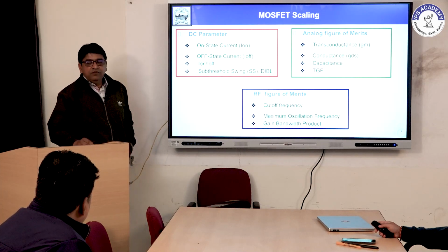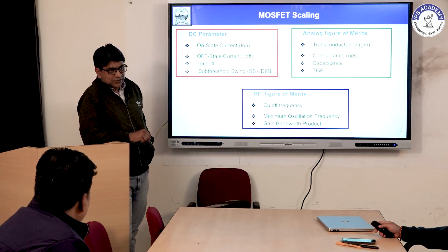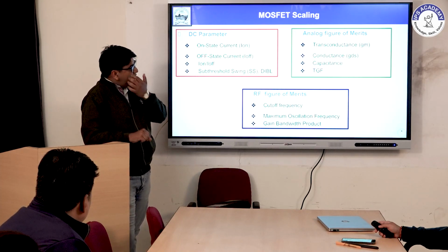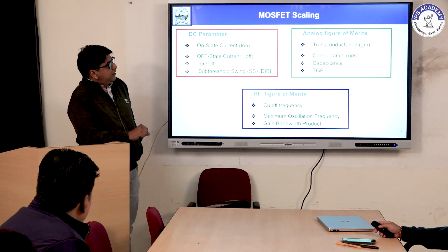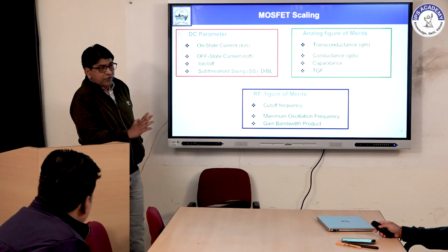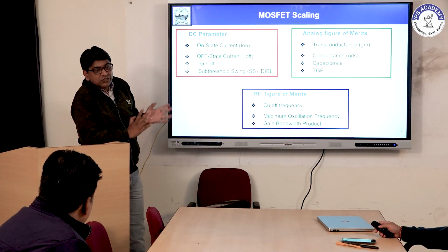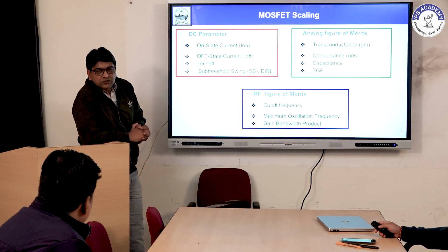These are the advantages. So whenever anyone is doing research work on biosensors, ultimately we are realizing such a device on some TCAD tool. So first, whatever the device we are going to realize, we have to check its DC performance and its analog and RF figures of merit, whether it is suitable or not. We have to keep them within limiting values. If not, when the sensor or device is used for the circuit aspect or sensor aspect, the device will be leaky, and that is not acceptable. So that's why the TCAD tool is there. So at the simulation level we can check all these aspects.